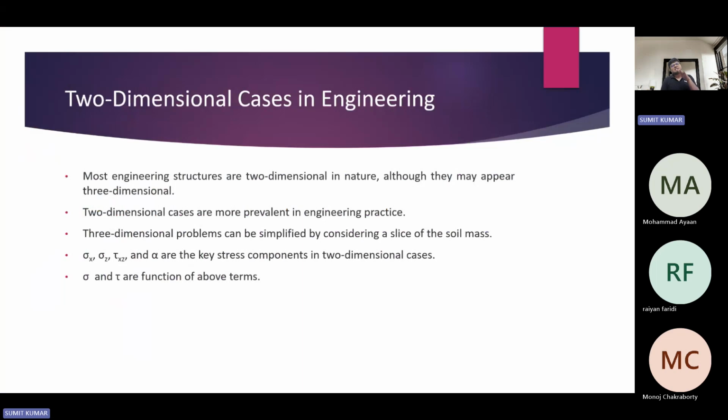Basically, the stress in the two horizontal directions below the ground surface is assumed to be the same, and the vertical stress which is acting over there, which also moving forward when we move to the triaxial stress over there, you see sigma 1 minus sigma 3 is the stress applied in the vertical direction. All right. So, okay. Once that point came, I will elaborate.